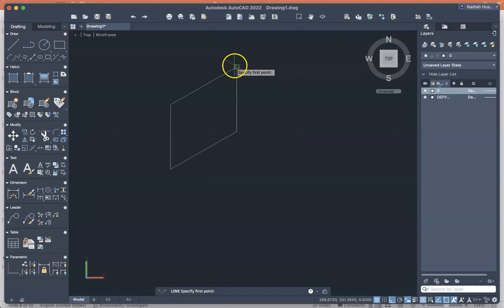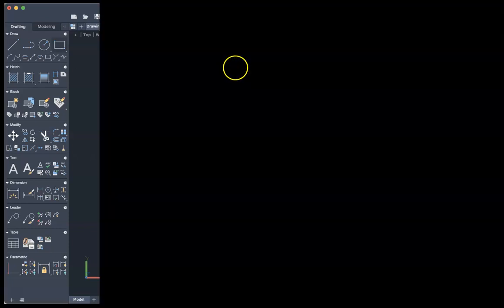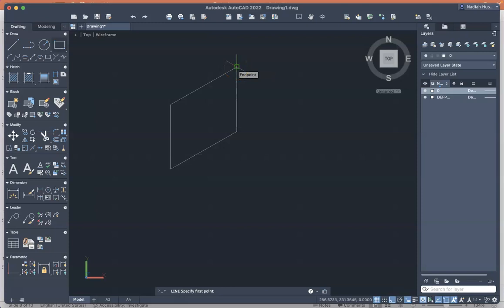Okay, so here we're going to use a line. I'm connecting it with a node. If you don't see this, click on your snap mode over here. No, this is not snap mode, this is ortho mode. Our snap mode is over here. Okay, so now I am connecting my line. I want to start my line over here. So now I am only able to extend my line here, upwards, and only downwards, because I am only able to go within the red and green axis.